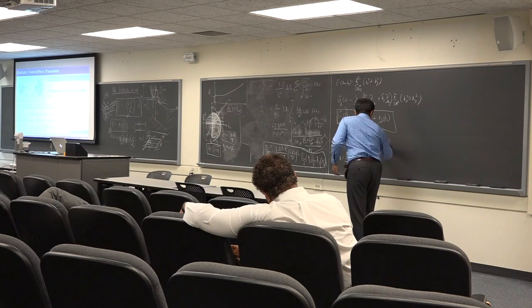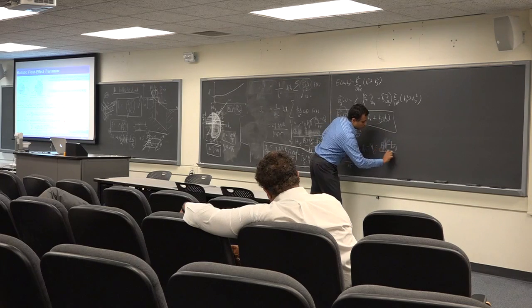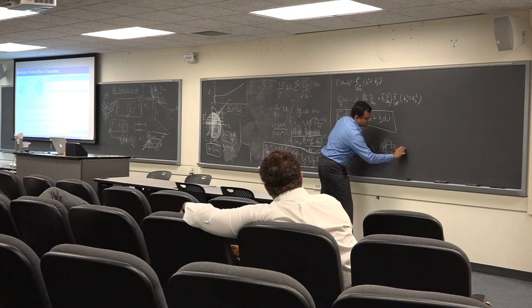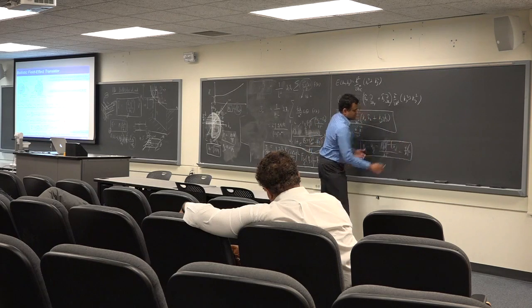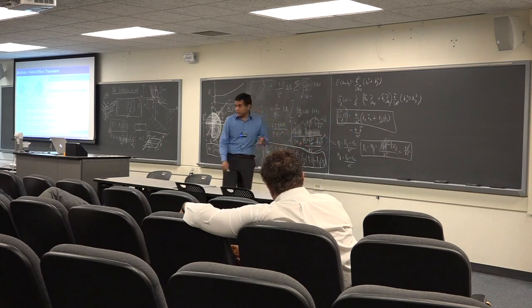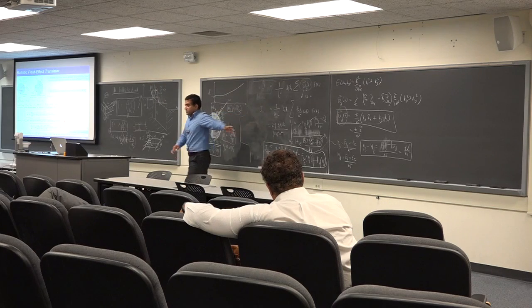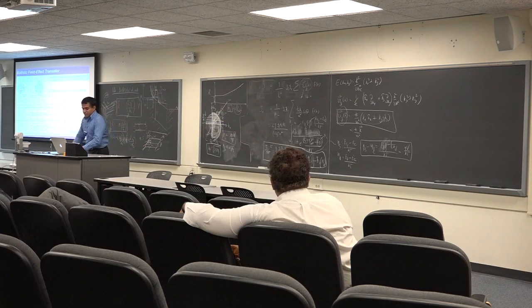So just like we had for the 1D conductor, that's q times the applied voltage. Let me write the whole thing. Fermi level of the source minus Fermi level of the drain over kT. So that's qV over kT. Right? So that's the equation for the difference of the source and drain Fermi levels. Is that clear? It's exactly the same, really not much different from what we had done earlier.